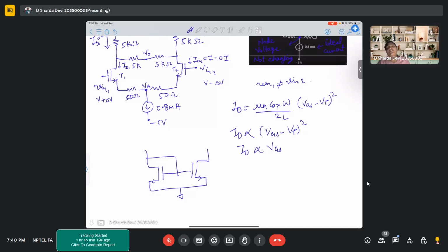So you were talking about, okay, let's say, will there be any voltage mirroring in that case? Yes, ma'am. Okay. So let's say the current is ID flowing through this particular transistor. Since the VGS is the same, both the transistors are perfectly matched, and I'm stressing on the word matched. Okay.